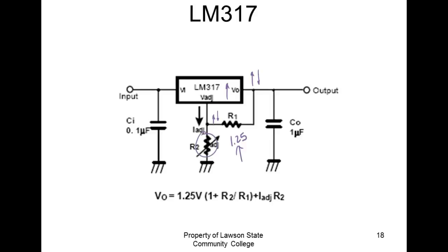So this is an LM317, great guy. Like I said, I'm doing something to get more current out of it. I'll show y'all the schematic on mine. It's not hard to do. I've actually got this driving a big transistor or 2 big transistors to get a lot more current out of it than it's capable of doing. And I'll show you how to do that if you wanted to make a nice variable power supply.